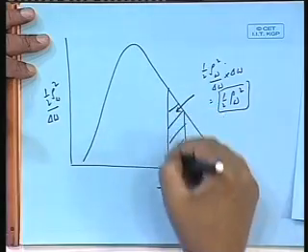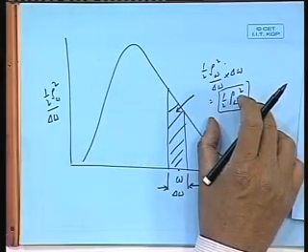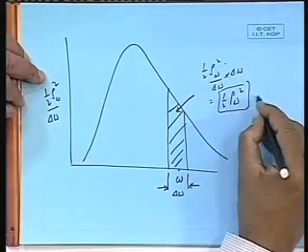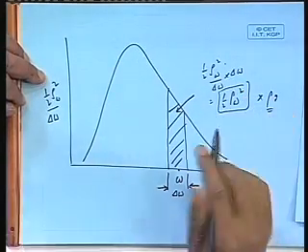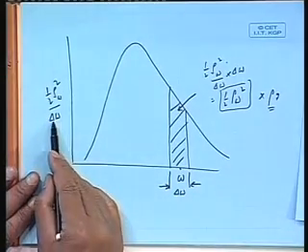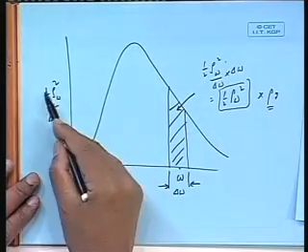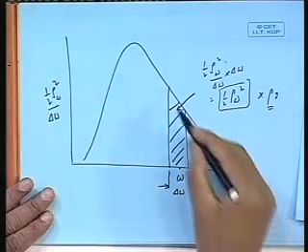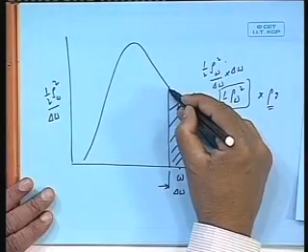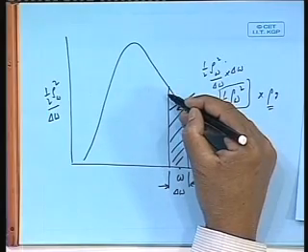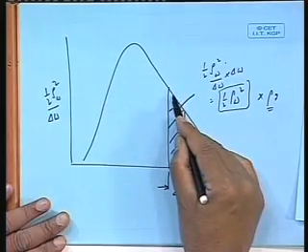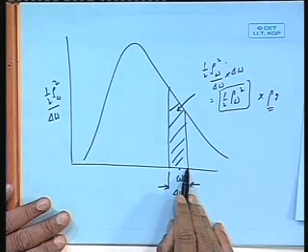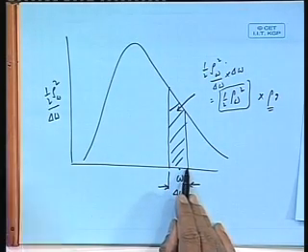This area is equal to energy, because multiplied by rho g it will give you the energy. So if you plot this quantity, that would represent a quantity proportional to the energy of all the waves of this frequency band, instead of just amplitude square.